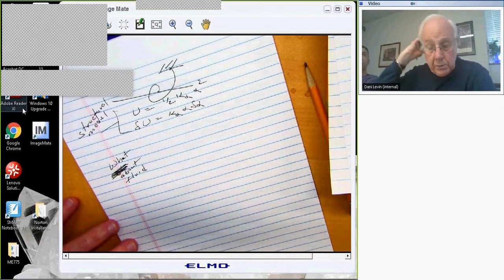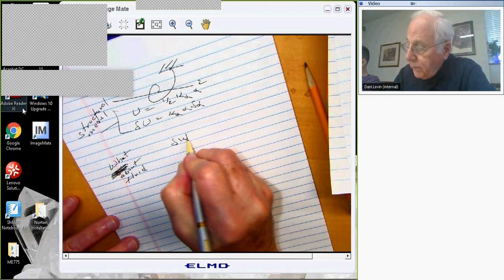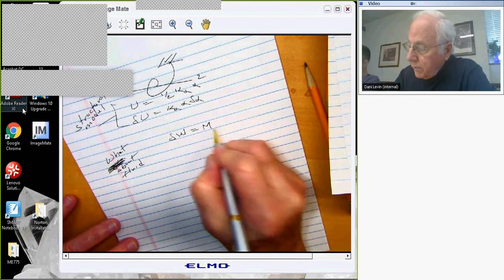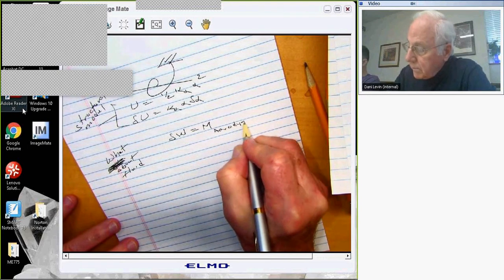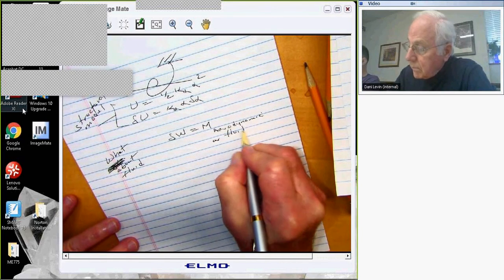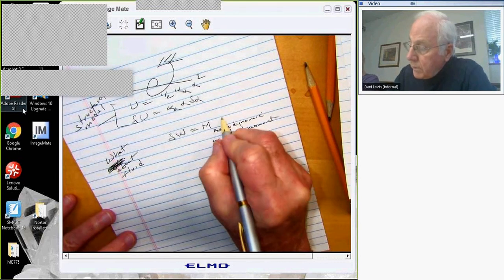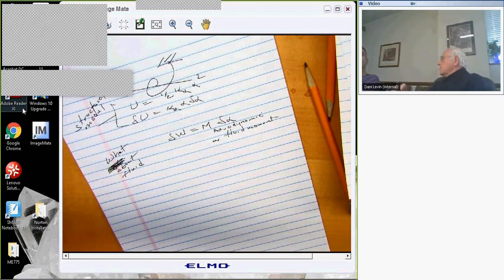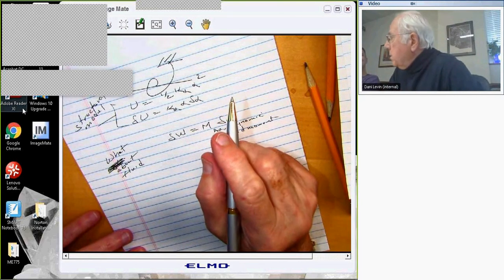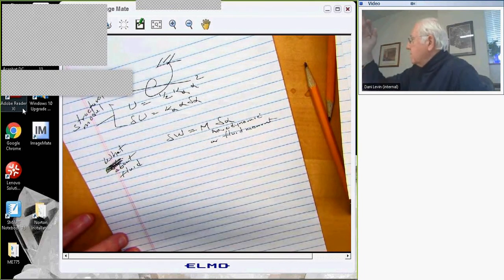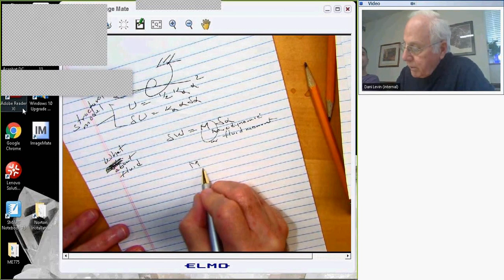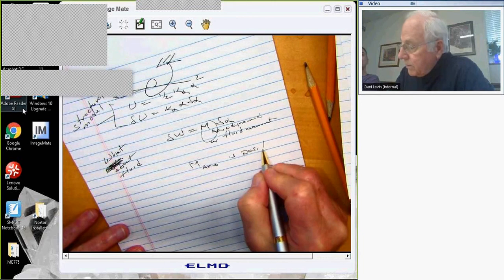Well, we have to compute the virtual work due to the fluid, but that's going to be the aerodynamic moment, or the fluid moment, times delta alpha, right? And just to confuse you, after all, remember aerodynamicists and structural people grew up separately and didn't talk to each other until later in life. It's usually the case that the aerodynamic moment is taken as positive in the same direction as the motion, or in this case, the static angle of attack, right? So this M aero is positive by convention or tradition.